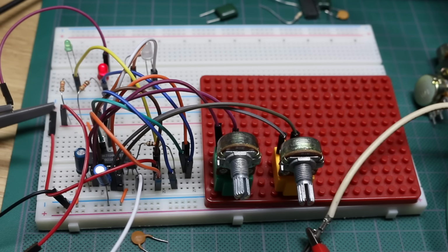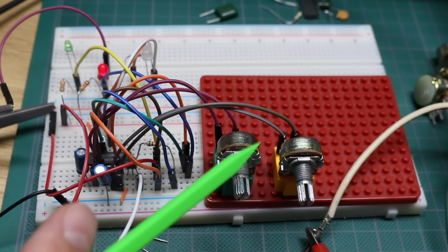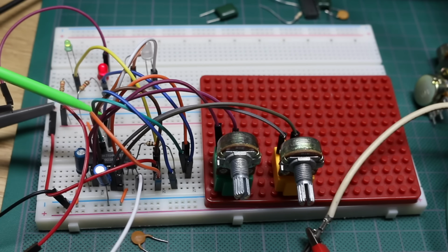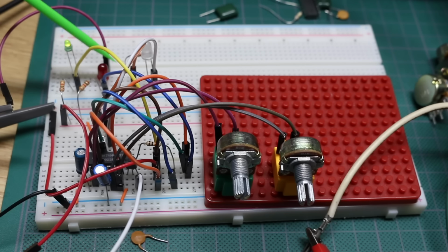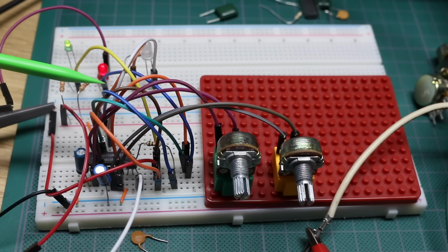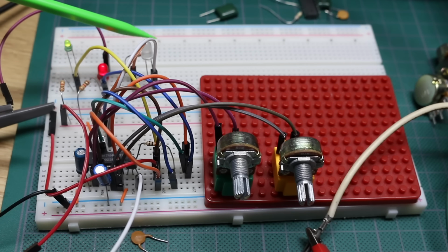Now I have a whole lot of stuff hooked up. I made 2 Schmitt Trigger inverter oscillators, and I can adjust the frequency independently with two potentiometers. And on the output of each oscillator, I have an LED, so the frequencies are set relatively low. We have a fast blinking LED and a slower blinking LED. Then there's a third LED connected to another NAND gate, where input 1 is a fast oscillator and input 2 is a slower oscillator. So it ends up giving a blink pattern that's gated.